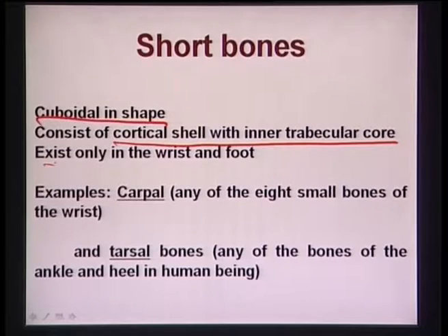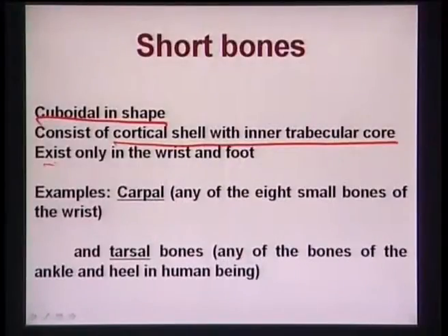So that is the reason this concept is very natural. That is the reason people always put coatings on the surface. Coatings are typically harder than the substrate. So whenever you put coatings like titanium nitride coatings on titanium or some other examples, titanium nitride has much higher hardness and much better wear resistance than titanium. So that is the reason why coatings are placed on a soft substrate.